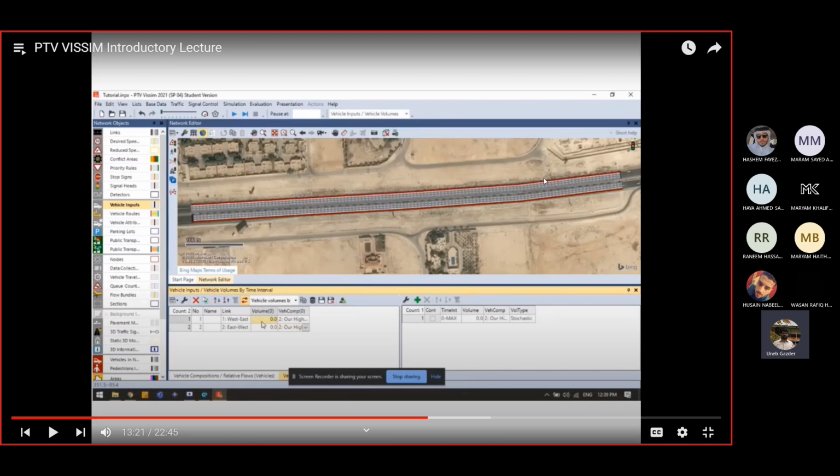So like you mentioned in the video, if you just move one direction away from the other direction, the software will take it as a median. Okay, and this is enough for level of service calculations. If you go back to the calculations which we have done in the class, in those calculations we never specified the width of the median. We just specified whether there's a median or not, and this is enough.